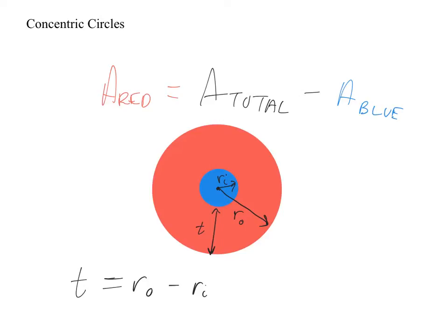Insulation, very good. Think back to the end of the year last year, we talked about heat transfer, and one mode of heat transfer was via conduction. There's conduction, convection, radiation. If you have a thicker wall that's insulating, you have a greater thermal barrier. Thus, the coolant or the heated fluid will remain at the temperature it is while traveling through the pipe. If you have a hot water pipe that is not insulated and it's running through the course of several yards, feet, meters, whatever, it's going to lose temperature as it travels through the pipe because the pipe is metal. Metal is a conductor. The conductor takes the heat, gives it off to the outside environment. So you need a lot of insulation. The wall thickness there, T, is the insulation.